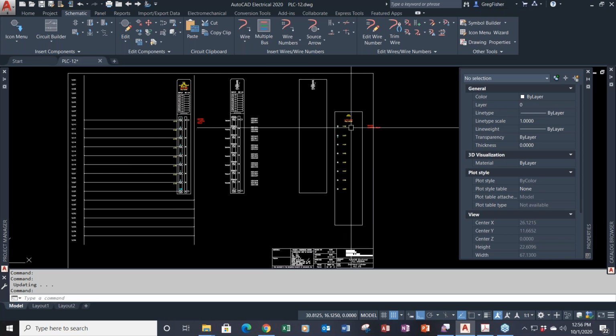So one of the biggest things to take away from these full units: symbol naming convention. Start it with PLCIO. With the parametric, it creates the symbol name for you after you insert it. It basically creates a block on the fly, and the symbol naming convention is the same thing. The first 5 characters will be PLCIO.